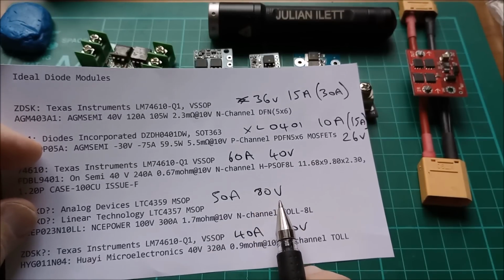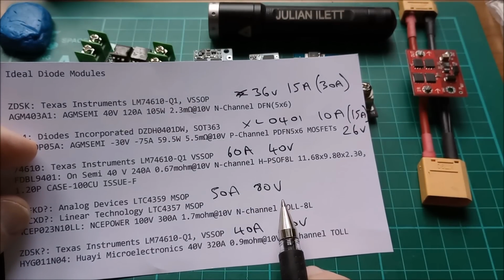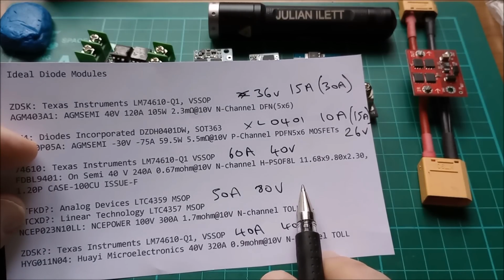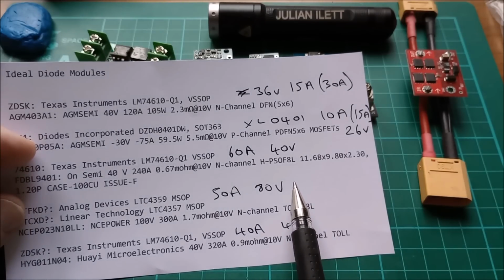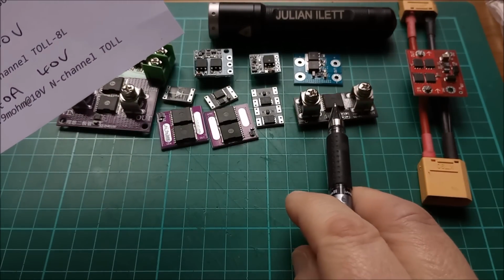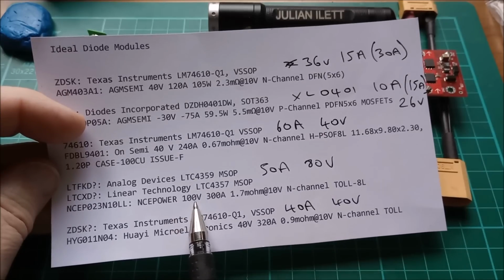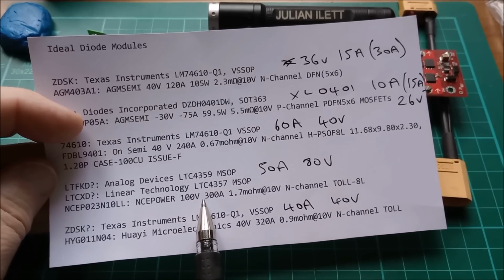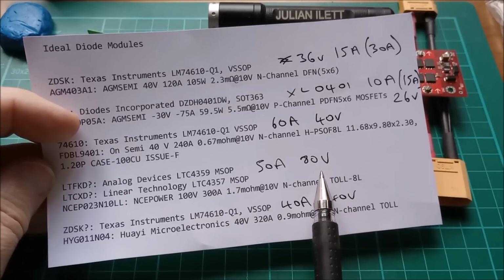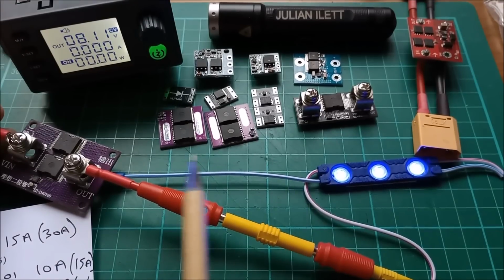Yes, on the datasheet it actually says the absolute maximum rating for in to out is minus 100 volts to 100 volts. So yes, that's what the chip will handle. And then this particular MOSFET they've chosen is this NCE Power 100 volt VDS. So that can also handle 100 volts of effectively reverse bias or drain source voltage. So just going back to the